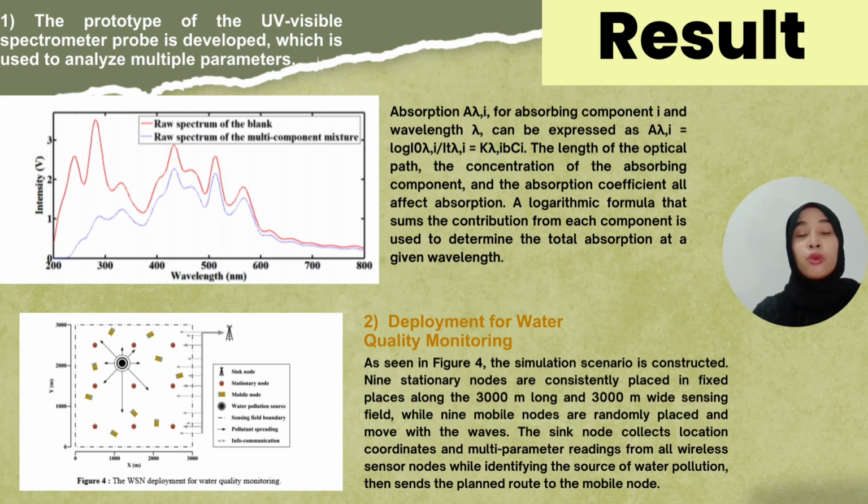The wavelength range of 200 to 800 nanometers is where the spectrometer works. The spectrometer reduces the error from the Beer-Lambert equation by measuring absorption correctly over a range of concentrations by changing the optical path. Measurement can be made with accuracy and reliability because these corrections are made in situ.